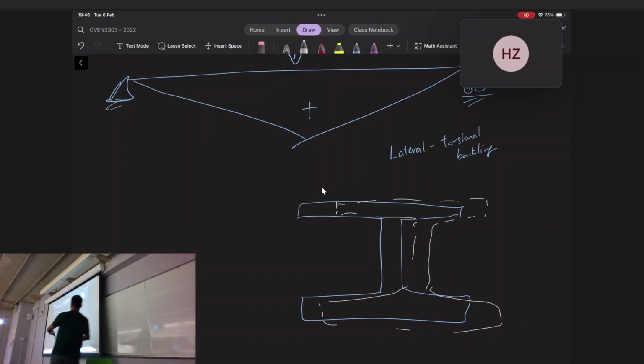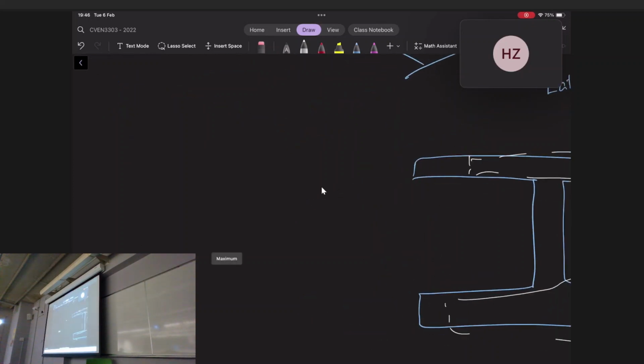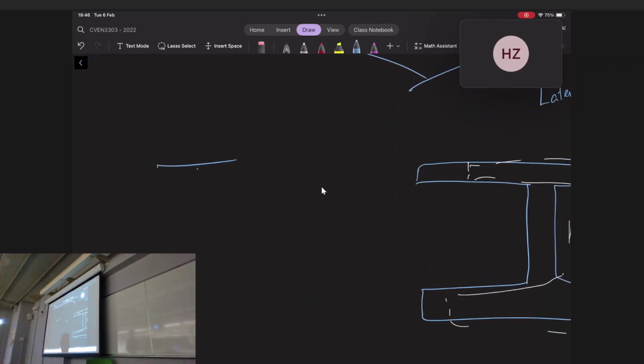Okay, so imagine this sticking out of the board. If I apply a strong enough load on it, what will happen is in the middle of the beam, right? Let's say there's a pin support on that end, there's a pin support on this end, right? If I apply a strong enough load on it, this cross section will move, translate horizontally. And the next thing it will do is it will twist. So maybe I'll show you this way is better. Imagine that is sticking out of the board, right? You will get something that ends up looking like that.